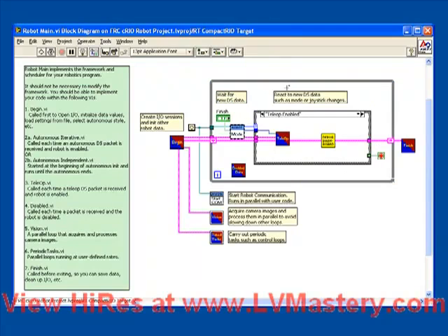And for those of you who have done testing, you may have actually observed that the time at which the Tele-Op runs is actually variable. Sometimes the delay between Tele-Op executions is as low as 5 or 10 milliseconds, and sometimes it's as long as 200 milliseconds. So if it takes on the order of 1/4 of a second for your motor to stop when a limit switch is tripped, that could mean permanent damage to your robot.